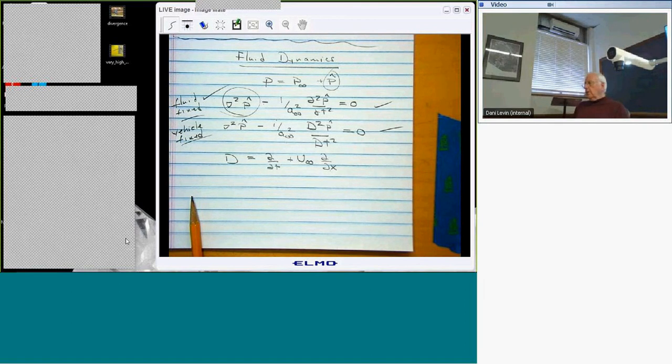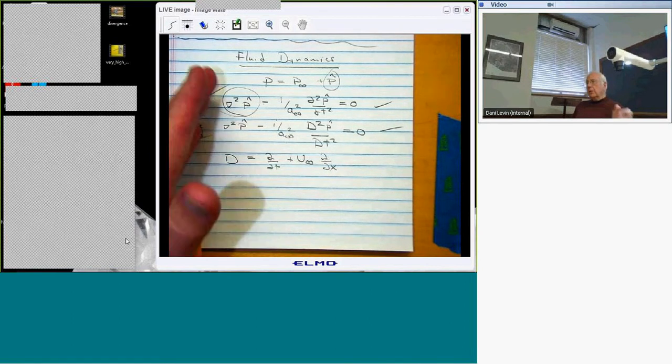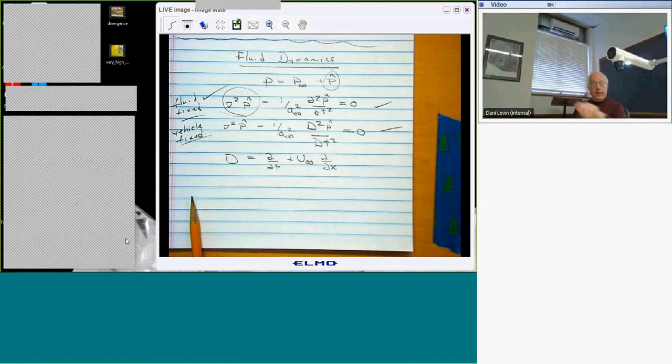Well, what about the heat equation? Actually, the heat equation enters in too, but not within this framework. When you're in low speed, as we'll see, it's Laplace's equation. In supersonic flow, it's mostly a wave equation. And in transonic flow, it's the transition between Laplace and wave, and that turns out to look sort of like the heat equation.